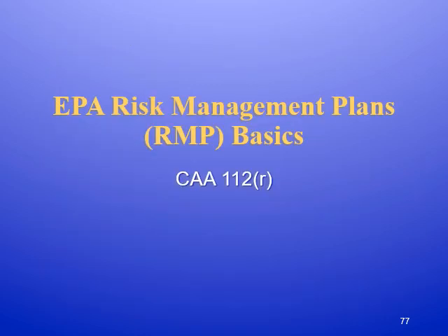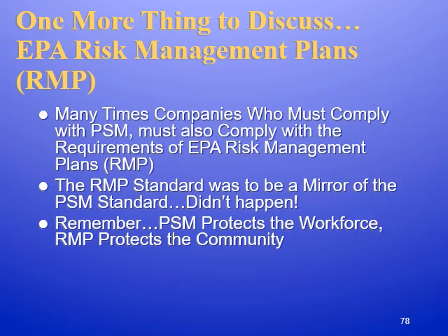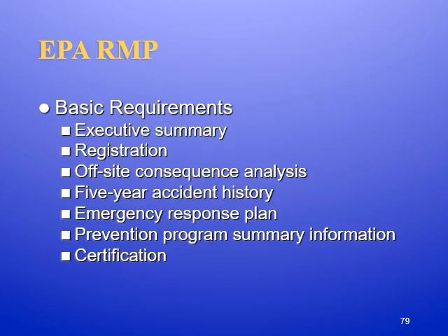So what is RMP? EPA's Risk Management Plan. Remember, PSM is OSHA, RMP is EPA. Oddly, it's covered under the Clean Air Act. Many times companies who must comply with PSM must also comply with RMP. The RMP standard was to be a mirror of the PSM standard. That really didn't happen. Remember, PSM protects the workforce. RMP protects the community. Basic requirements: executive summary, registration, offsite consequence analysis, 5-year accident history, emergency response plan, prevention program, summary information, and certification.